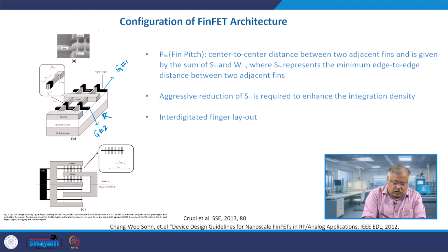Then this is also referred to as interdigitated structure, right, and the drain is common between this and this. So, you have a source here, you also have a source at this end, and therefore, typically you have 4 such devices inbuilt within them, where the drain is being shared between all the 4 elements. As you can see, this is basically a TEM image here, and this is the gate.